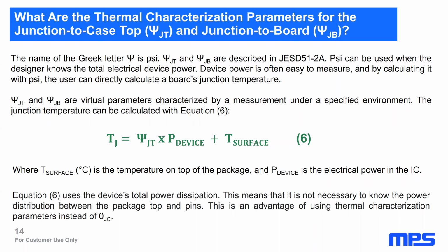And this equation is almost valid for all custom PCBs. The Psi depends on the air convection, so it is measured on a free PCB where the air can rise up freely.